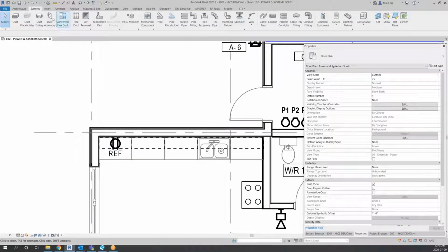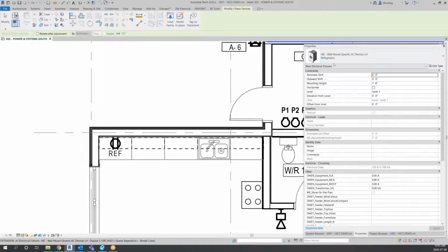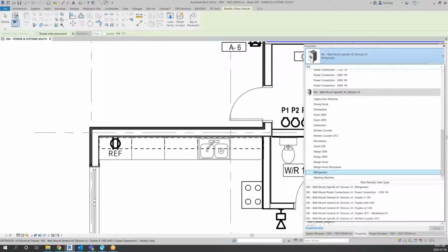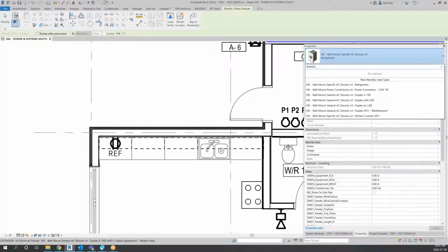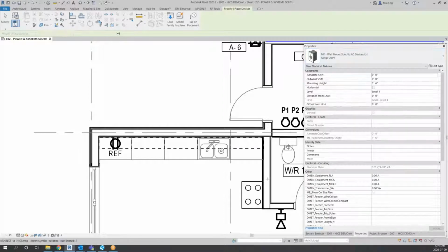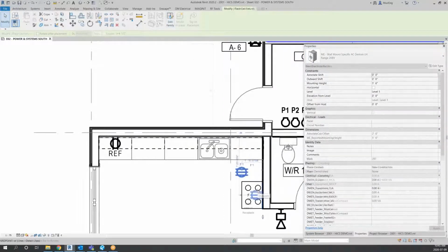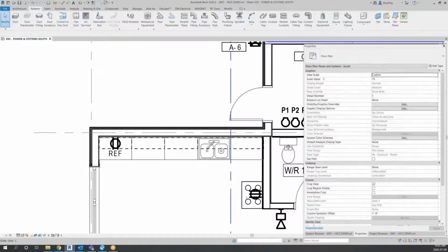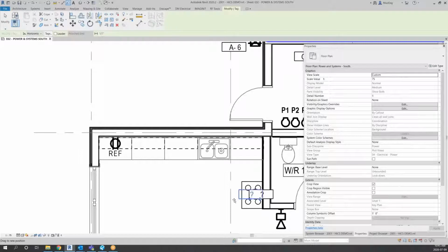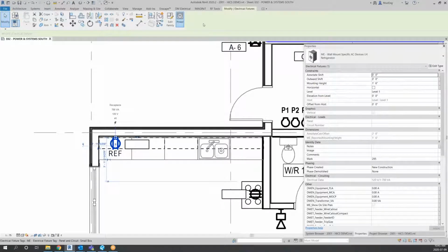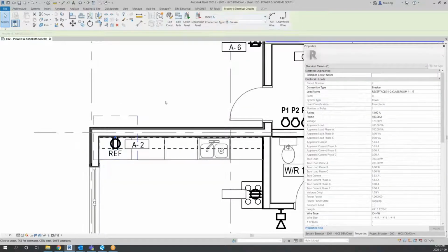I will also go and drop down another one, which I'm going to have as a range. Okay, so a 208 volt range. So here's a range, a 208 volt receptacle, right? Let's get a circuit tag on both of these. So right now we're not circuited either, right? So we're gonna throw those on our house panel. So panel A.